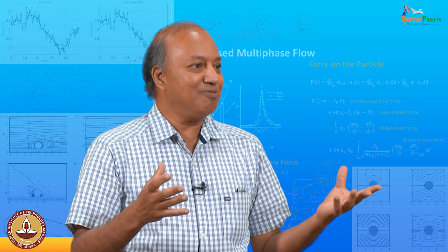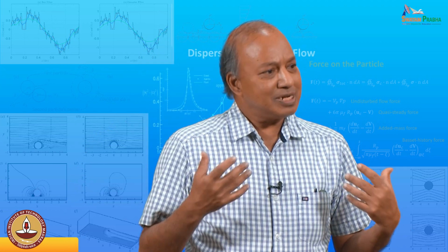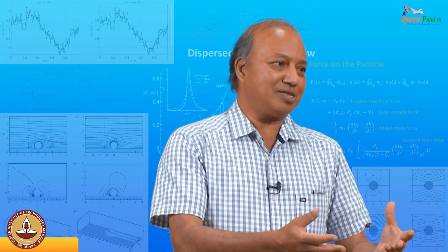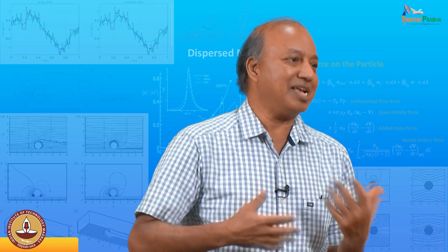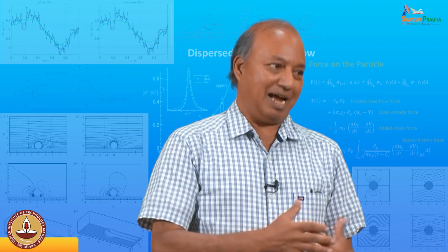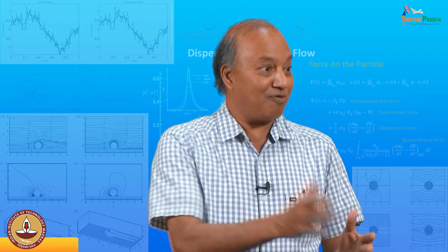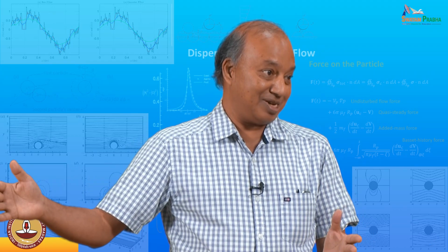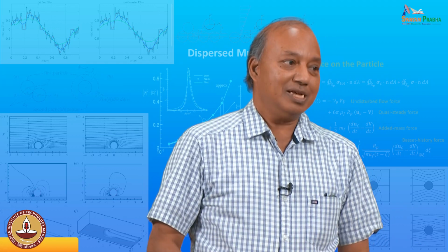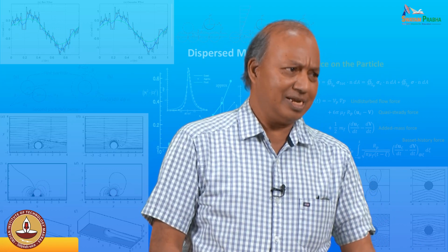You cannot remove that. Your statistics may be stationary, but when you watch the flow, it will ever be changing in time. Okay? So, the ensemble average will be time independent, because you have averaged over many realizations, and it will preserve the underlying symmetry, whereas the volume average will not. Did that answer your question?